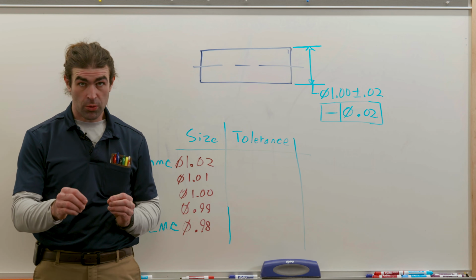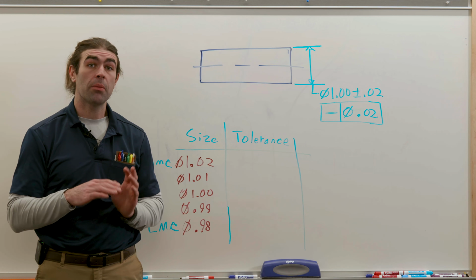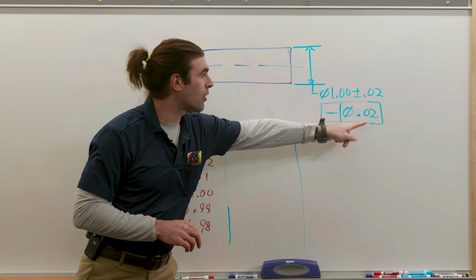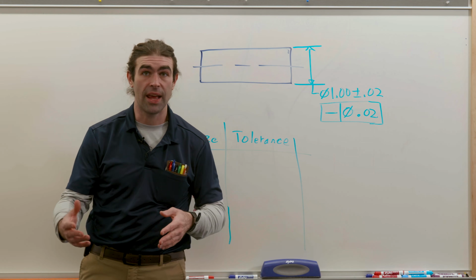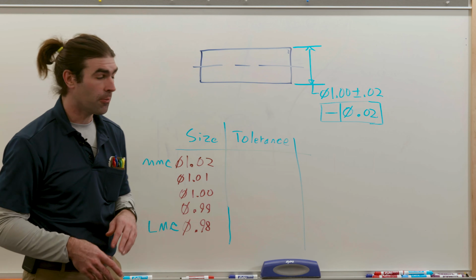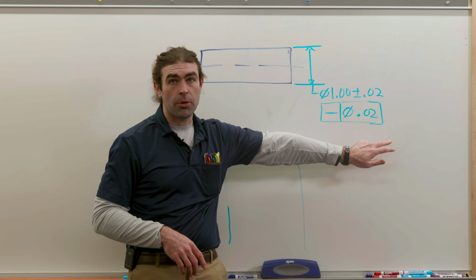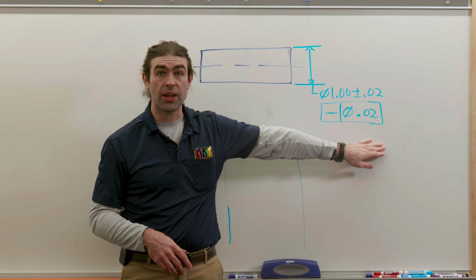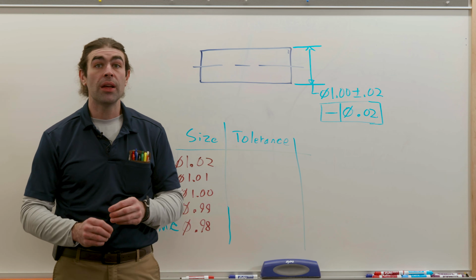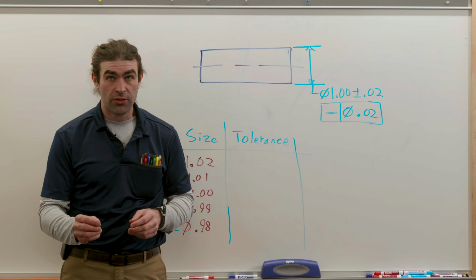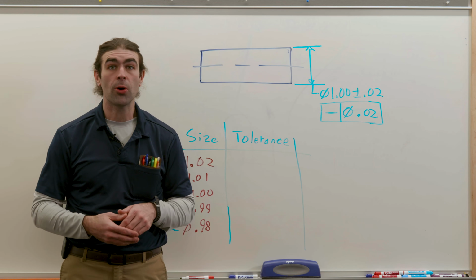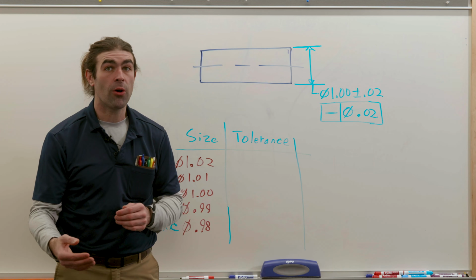This just means, real quick, that the center of that pin must lie within a cylinder that is 20 thousandths in diameter, and that's all we'll worry about for now. So, there's no MMC or LMC symbol, but it is a feature of size. In that case, regardless of feature size, the one where we don't use the symbol applies. It is the default requirement.